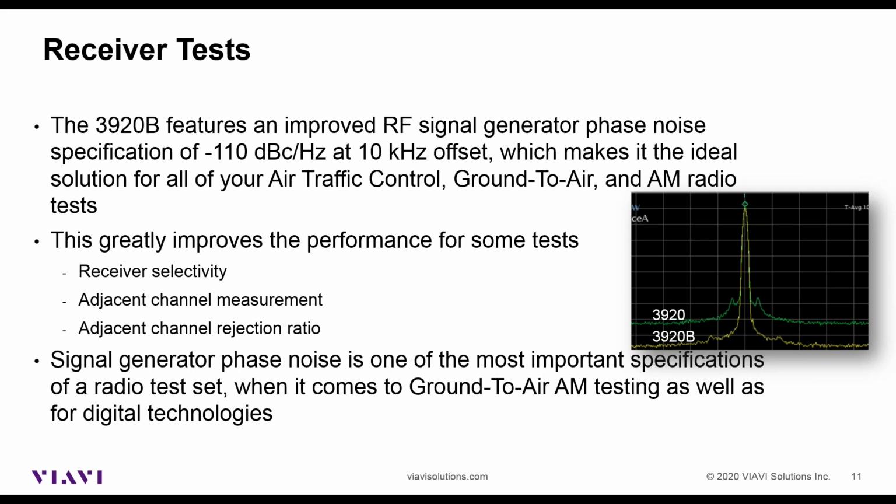And it is one of the most important specifications of the radio test set, and it impacts AM radios probably more so than FM radios or digital radios. The digital ones are more impacted by very close in phase noise, causing jitter.